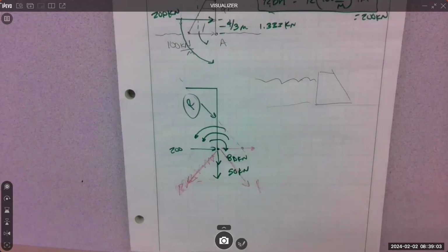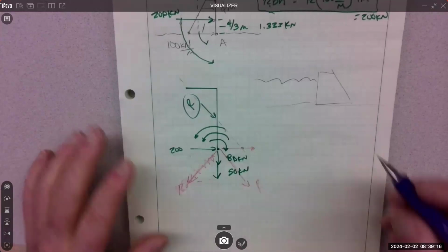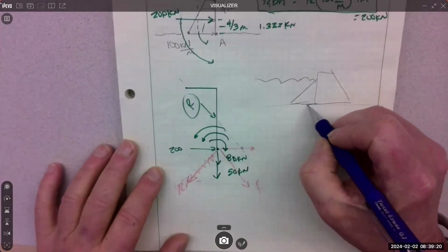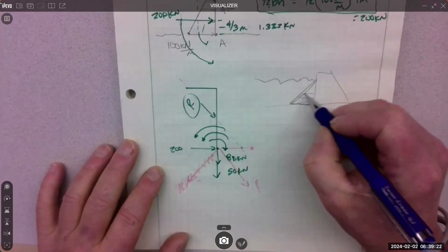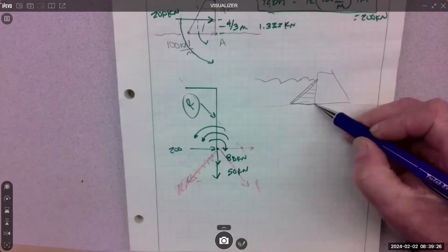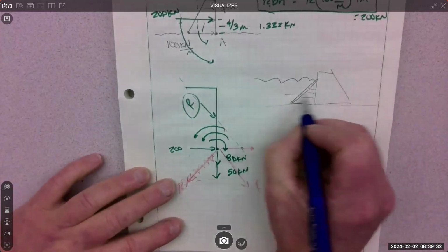So when we have this crazy meltdown in the spring and all this rain, everything's flooding and the river's rising, it comes up that dike quite a ways. Right? So if we build it right, that holds. So here's the deal, water pressure creates this kind of a load diagram, right? Bunch of pressure at the bottom where the water's deep, no pressure at the top where there is no water, right? So then that creates this.